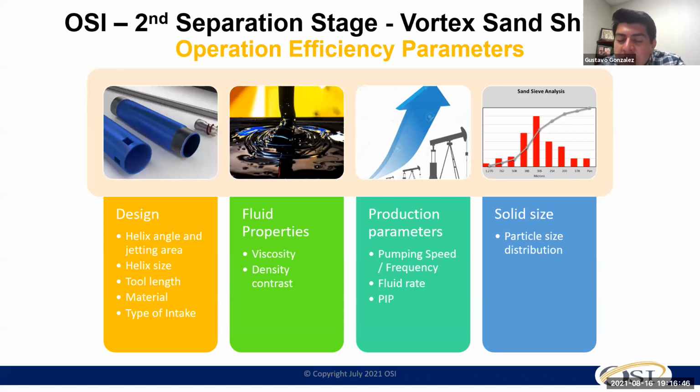The fluid properties, that's something that please have in consideration. Lighter oil, API like 40, 42, is not the same as dealing with 10 API oil. The viscosity is going to be different. The way that the same particle, that maybe is 100 mesh or 20/40, is going to behave differently in every single well due to the viscosity.